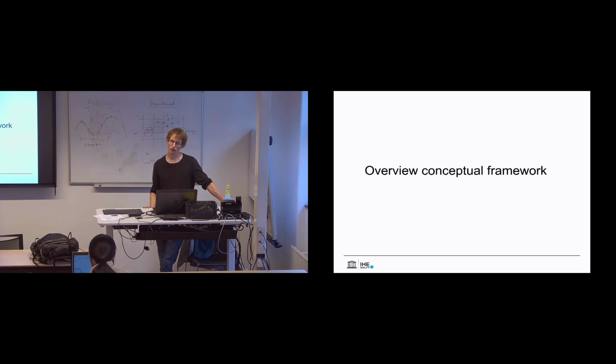Water quality can only work offline with Delft3D 4, but there is now an online version of flexible mesh. So you can do water quality simulations inside flexible mesh. It's just a flag that you can switch on. So you don't have to first do a hydrodynamic run and then do a water quality run, but you can do it in one run.